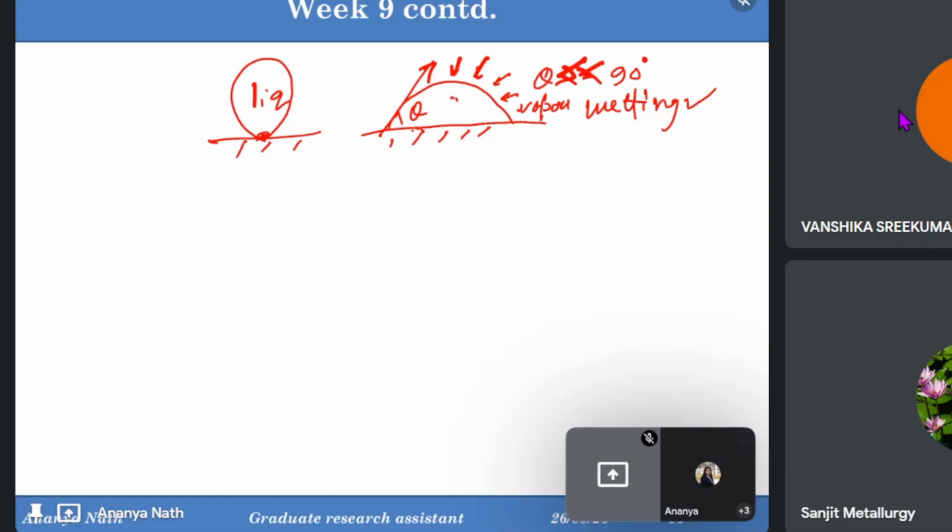Yes. Okay. So the next topic was the three stages by which the solid surface can be wetted and leads to the bonding. Because at the time of normal casting or melt infiltration, you are just pouring the melted aluminum in the mold, where in case of melt infiltration the porous preform of the reinforcement particles is present. In case of stir casting, you are just adding the particles as it is. But if the particles have some properties due to which they will not get that much wetted by the melt, then we can go for these three stages.